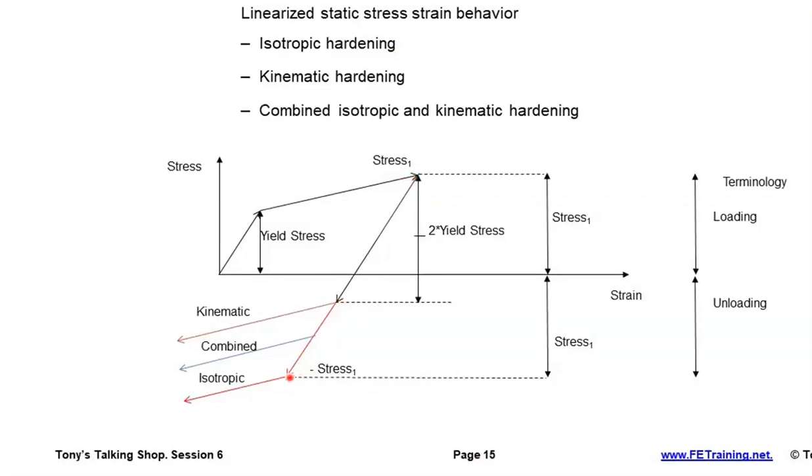Now, what model would we use? We typically would use kinematic loading in our typical fatigue analysis, but we could use either of those. It's material dependent. It's also dependent on the directionality of the stress and so on. But this could be one kind of approach. Now, for cyclic loading, we want to know what's going on there. So that's one of the things we need to understand.